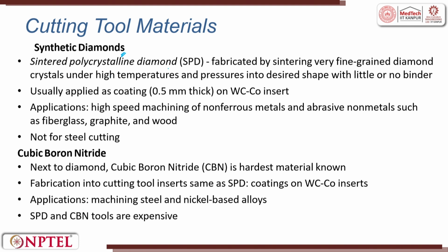Sintered polycrystalline diamond is fabricated by sintering very fine grain diamond crystals under high temperature and pressure into a desired shape with little or no binder. Natural diamond, synthetic diamond: carbon under very high temperature and very high pressure gives you a synthetic diamond. It is usually applied as a coating on the insert to get better properties.